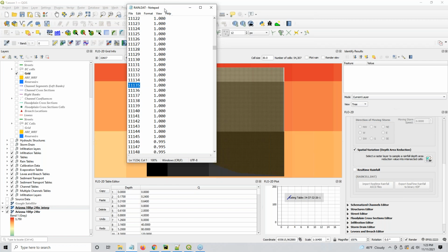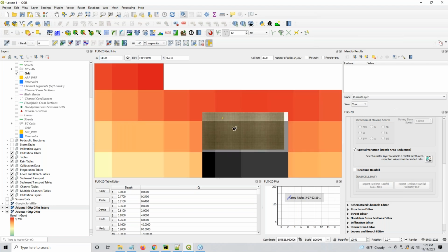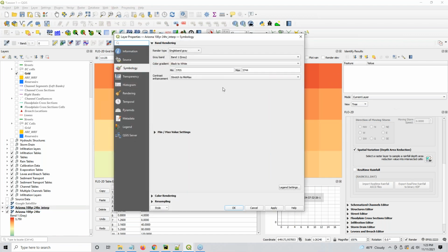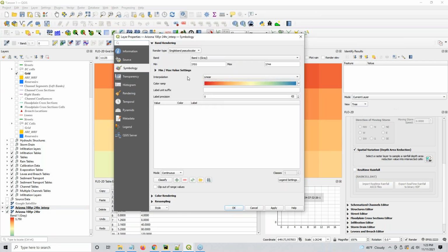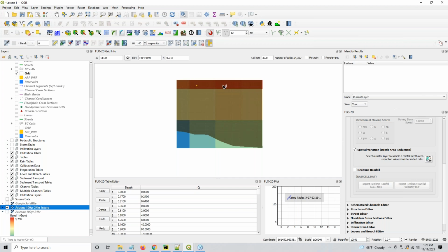And if I copy that, I'm going to put it in here. And I'm going to highlight it, and you'll see that, let's colorize this map too. We're going to colorize this map with single band pseudo color and invert the colors and classify. We don't need to clip the outer range values because we've already kind of done that by warping it. And click apply and OK. And now let's turn this one off. Okay, so now you see that we have our 3.744, 3.743.